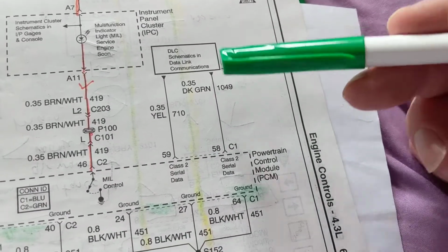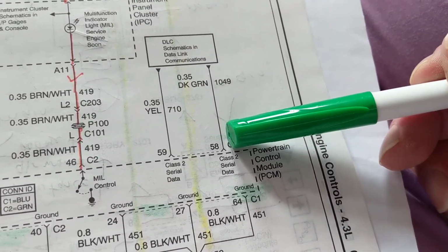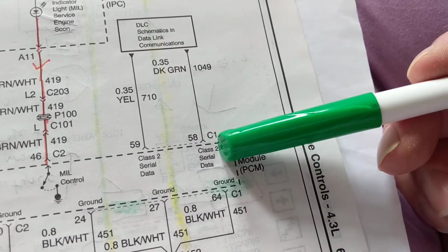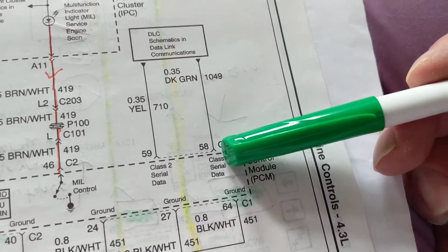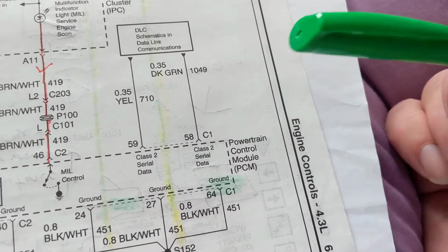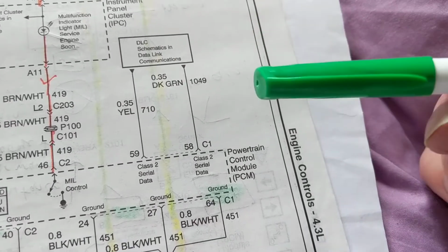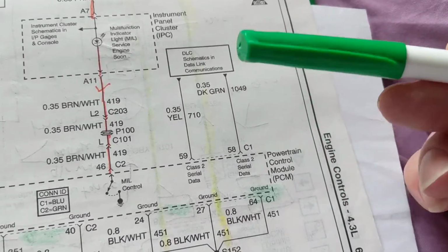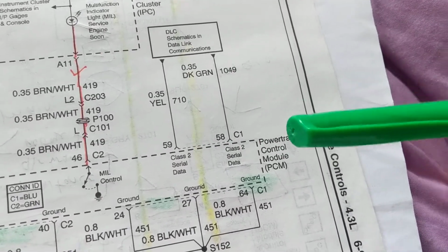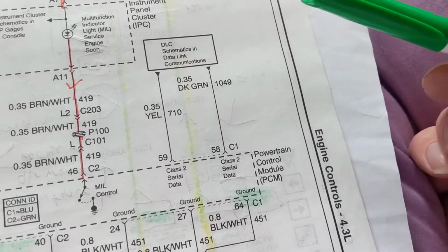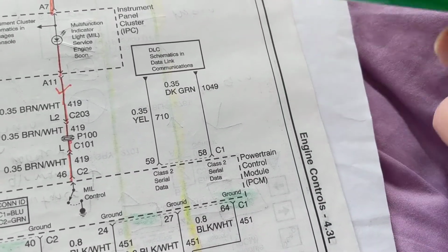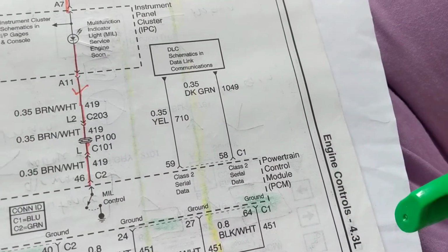He has to know how much air is entering the engine, the temperature of the air entering the engine, and the coolant temperature sensor tells him the temperature of the coolant in the engine. Why? Because he has to open and close the fuel injectors in order to get more fuel or less fuel into the cylinders based upon air. More air, more fuel. Less air coming in, less fuel I will pour into the cylinders.